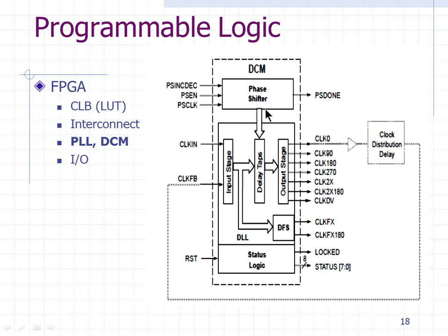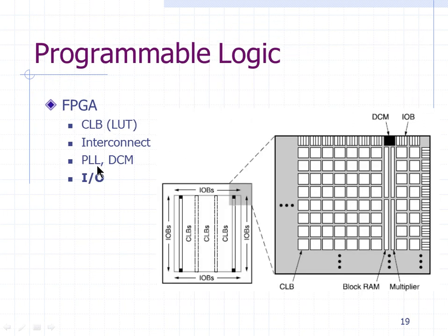So you don't have to write separate logic for it. You can directly use this block, which is a special block of the FPGA, and get the special clocks which are generated and then use them for your design purpose. So clocks are very important, and that is supported by this block and similar other blocks. IOs. There are input output blocks on all four sides of the FPGA. The input output blocks can also be programmed. All the pins can be input or output depending on what your requirement is.